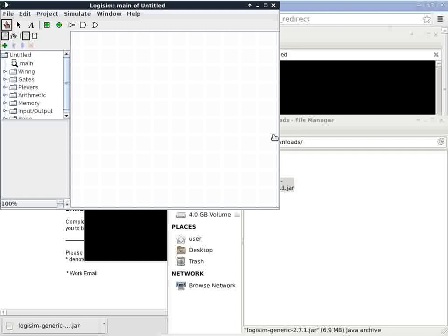So what I'll do is I'm going to design a half adder and then make a component out of it, and then use half adders to make a full adder, and then make a component out of that, and then I'll make a 4-bit adder. Your job is to make a subtractor, okay, a 4-bit subtractor. So what I'm doing in this class is going to be pretty much the same thing that you have to do in order to get your homework done.